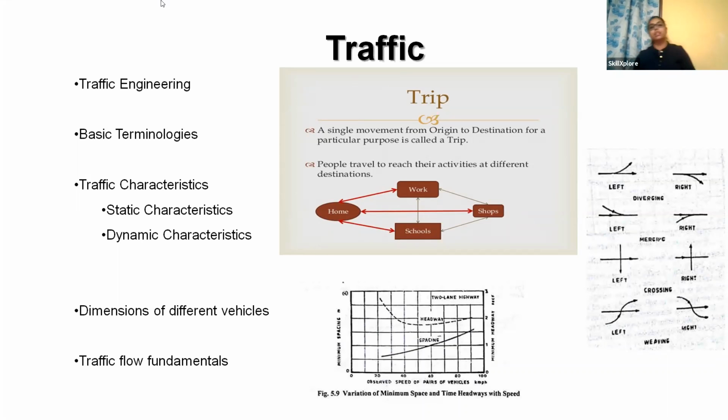Why do we have to know the dimensions of the different vehicles? While designing the pavement, the width of the roadway and all those things, the dimensions of the vehicles come into play. In rural areas, more trucks will be there, and in those areas, while we are designing a pavement, we have to know the width of the vehicles we can expect in that area, right? And also, while we are designing an underpass or overpass, there will be a roof. While we are designing a tunnel, there will be a roof, no? So the height of the vehicle comes into play there. So we have to understand the dimensions of the different vehicles.